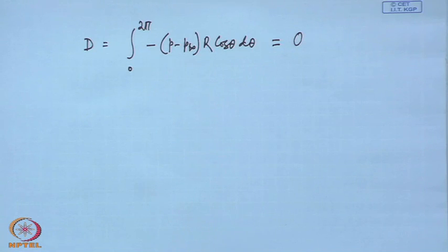We have assumed that at very high Reynolds number, the viscous effect will be confined within a very, very thin region, which is basically negligible when we consider the entire flow field. And we see that as far as finding velocity, at least if not for circular cylinder, because the circular cylinder case is a little different, even though we have solved the flow for circular cylinder, but we will tell why circular cylinder is a little different from others. When we apply this to airfoil like bodies, we really get very good results as far as lift force is concerned, even the pressure field, velocity field, but when we come to drag, it gives straight away 0, even for a circular cylinder which has a very high drag coefficient.